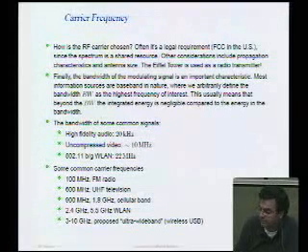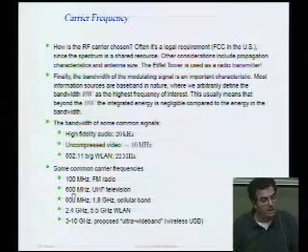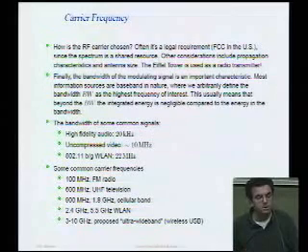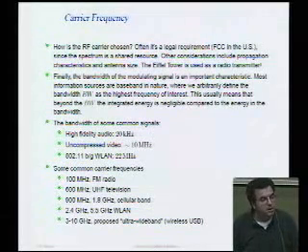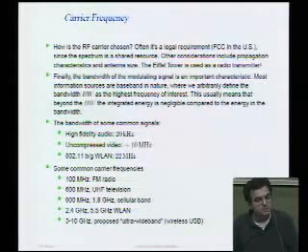An example of a spectrum that people would really like to go after is this UHF spectrum. And the reason is that UHF is probably one of the sweet spots in the spectrum in the sense that you can get very good long-range transmission with reasonable antenna sizes. It's very good at bending corners and going through trees and walls and whatnot. And the frequency is still low enough that you can build very low power circuits. So it's almost like an optimal frequency for building, let's say, wireless internet.